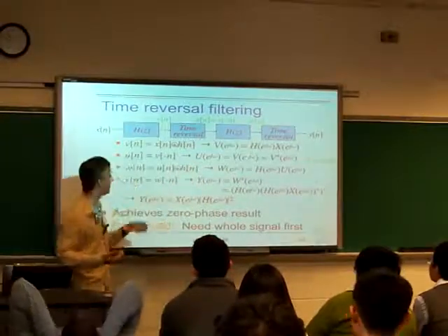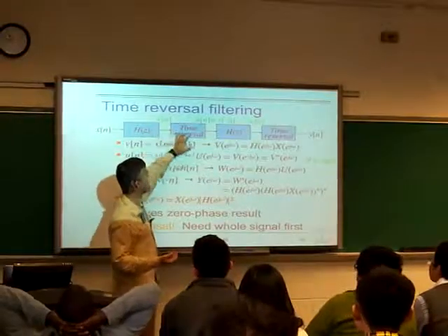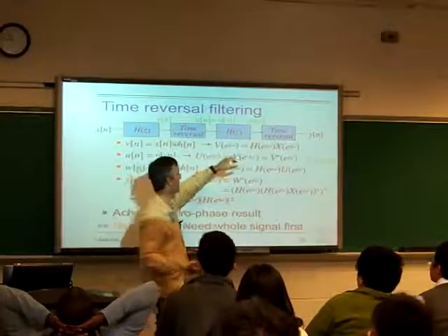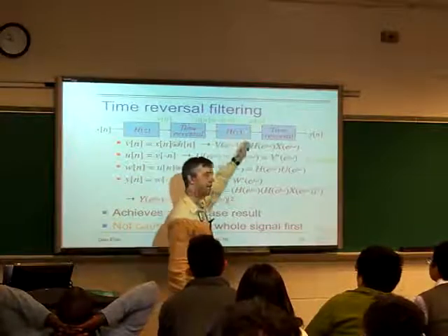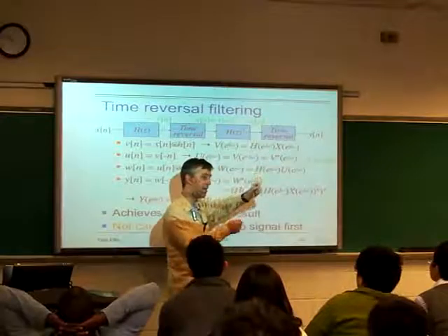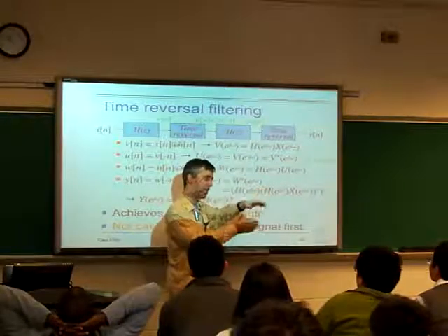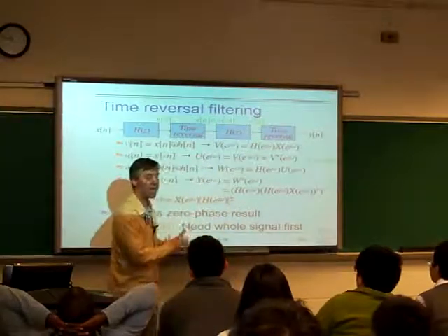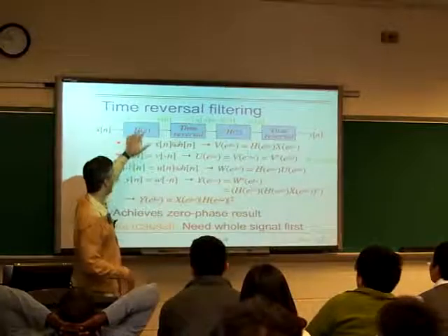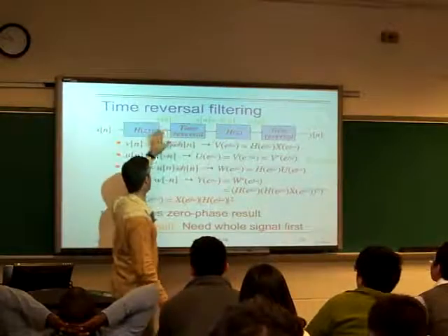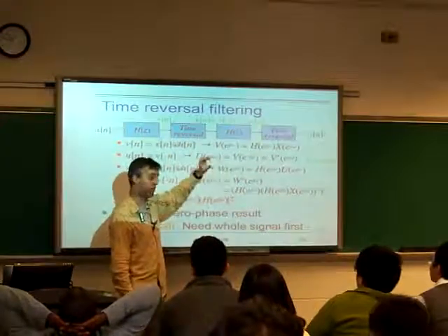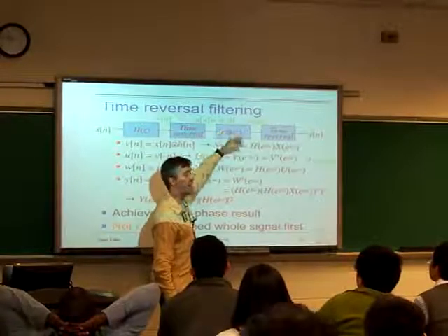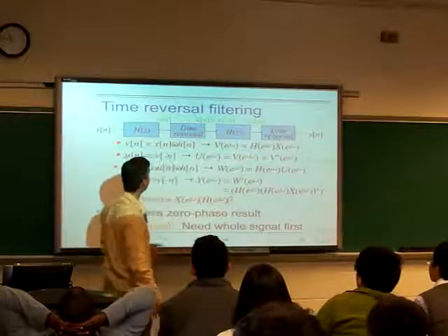And the idea is that if there's a frequency which is delayed by a certain amount when it went through in the forward time sense, when we put it through in the backward time sense, it'll get delayed by the same amount, but now time is looking the other direction, so that delay will shift it back to zero phase. And so we can get an overall cancelling out of the phase response, although the gains of these two things will compound. If we're reducing its amplitude by a half here, we'll reduce its amplitude by a half again here, so it'll be an overall gain of a quarter.